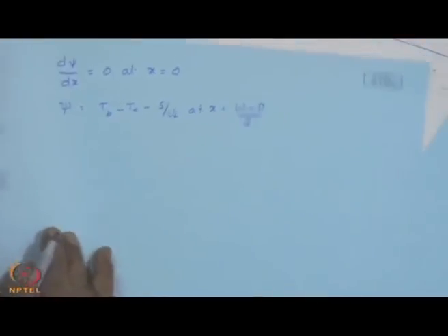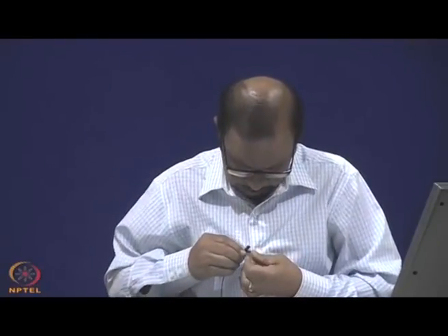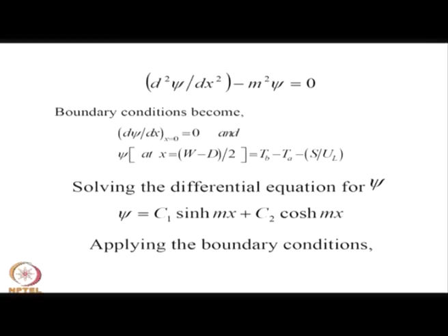so we have set up an equation in the x direction. We had considered half of a repetitive element from the midplane of the sheet up to the beginning of the tube, and you should be familiar with this equation in heat transfer.